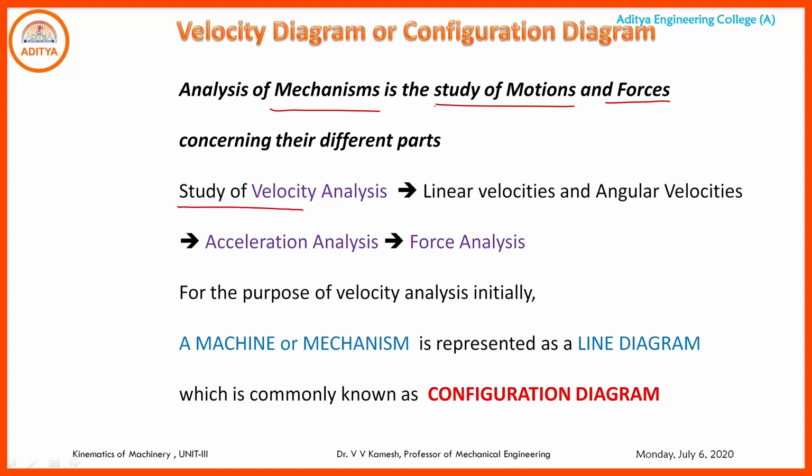And the study of velocity analysis is the first thing. First we will analyze the velocity, what are the different linear velocities and angular velocities, and this velocity analysis will be an input for acceleration analysis. That means velocity diagram is the first step.